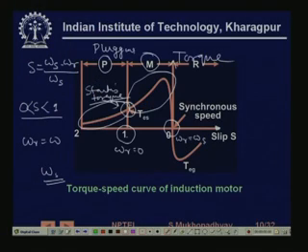This is called plugging mode and is generally not used for braking. There is another braking mode, apart from rheostatic braking, which we are not considering here, where you just connect the rotor circuit to a set of resistances, typically done in wound rotor machines.